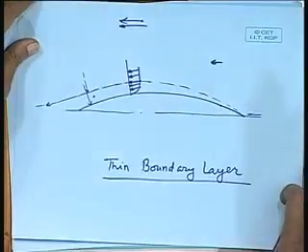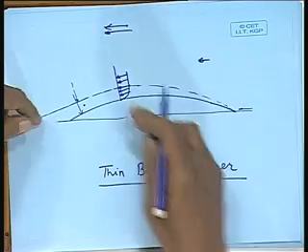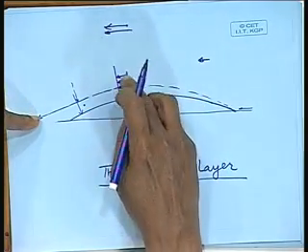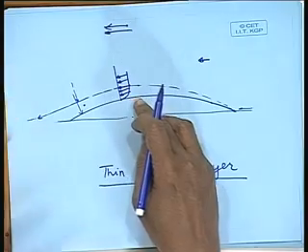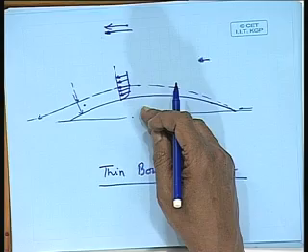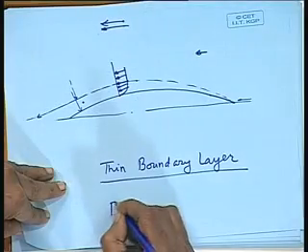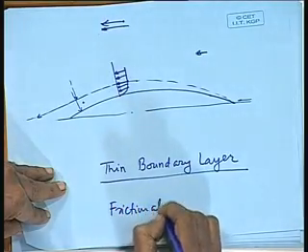In the previous case, I did not complete this because of the tangential forces between the layers and creation of this boundary layer, where you see that a mass of water is following the ship. That energy that is given to the water so that it can follow it comes from the ship. Otherwise, how can the water on its own start moving? That energy that comes out of the ship is what we call frictional resistance, purely due to friction. Okay. So, this gives frictional resistance. We will look at this in more detail later on.